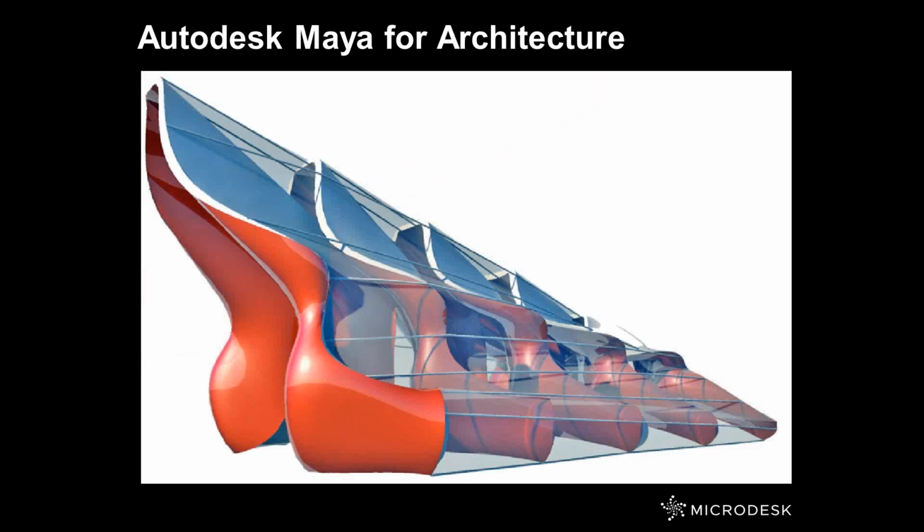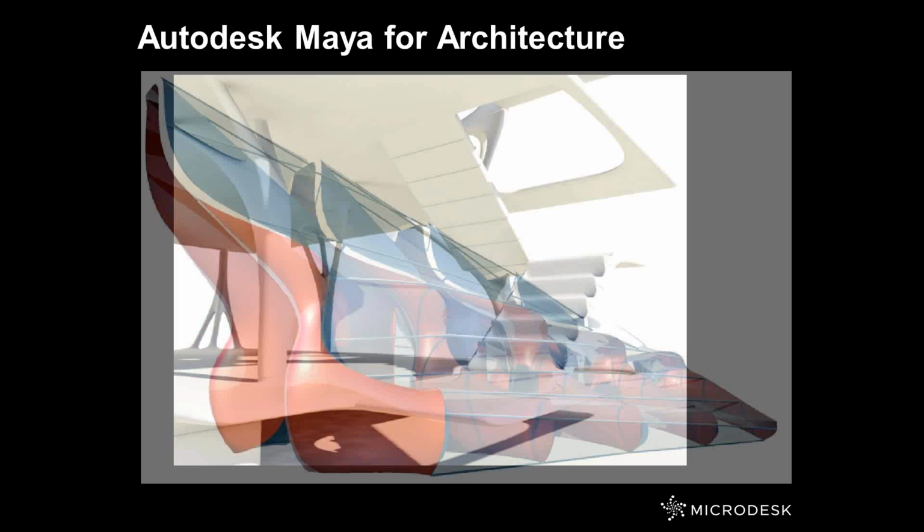This is another example of a structural envelope of connected structural shells, and it's nothing other than a loft surface between different solids and individual surfaces that are assigned a transparent material. And there are things called isoparms and extrusions that create those mullions that you see in between. So you can definitely generate something very complex in a much shorter amount of time compared to other applications that are not designed to do this kind of work.